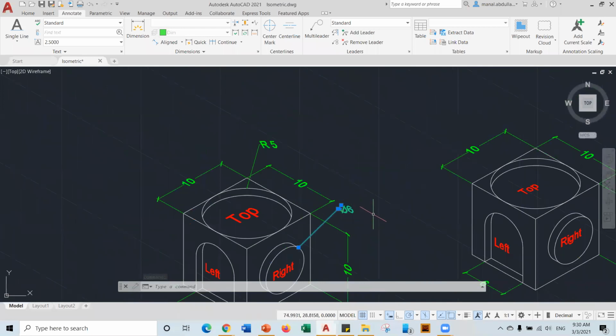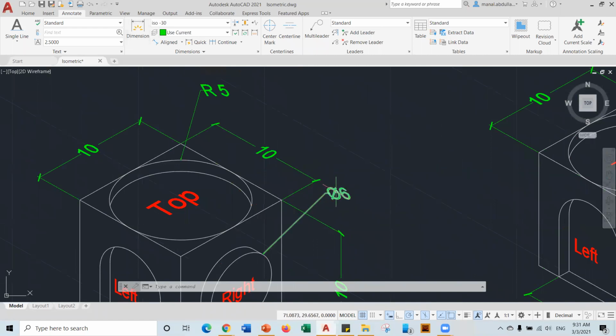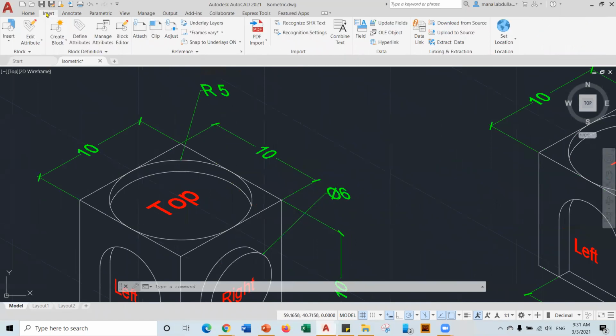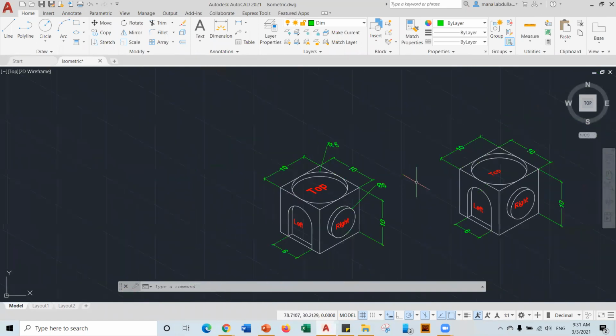Okay, so you can modify the text style to apply the text style that you created, or from the properties and add. So remember that radius and diameter with the isometric drawings will not work the same way with dimensions. So you have to create multi-leaders. You put R, you type it, and then for the diameter, you can either insert symbols. If you need to get some symbols, you can find that, or you just put %C for the diameter symbol. Okay, I hope that will be useful for the isometric.